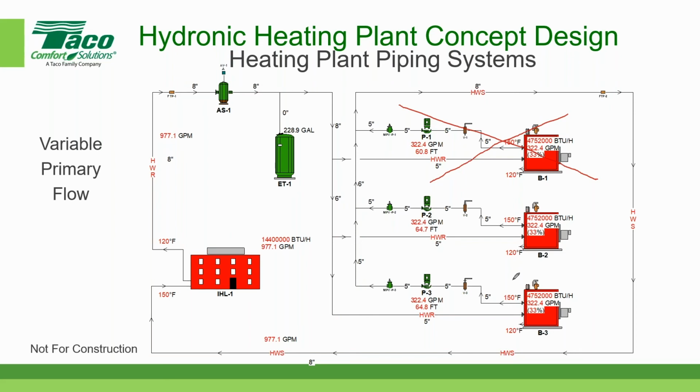In Cranston, Rhode Island, we're using panel radiators on the external parts of the building, and we are supplying water temperature around 100, and I think it's around 160 degrees, and we have about a 30-degree differential. So our return water temperature typically comes back at around 130, which is within the range of our condensing boilers. Okay, so that's primary, variable primary flow.